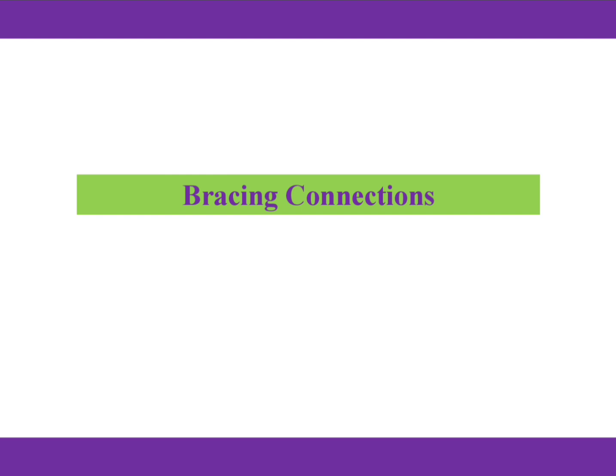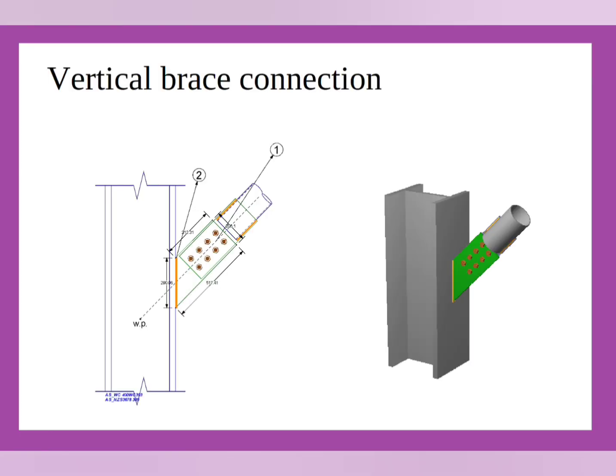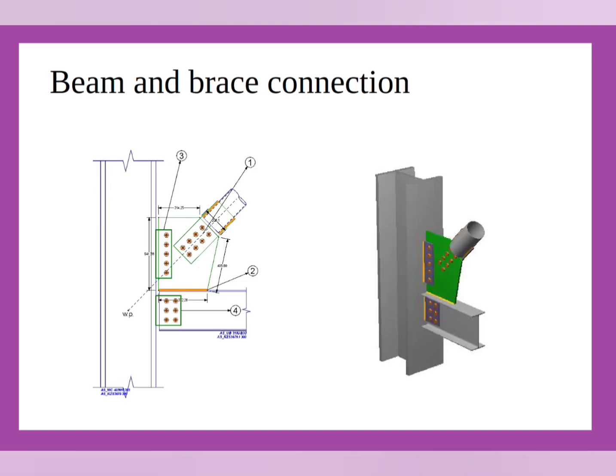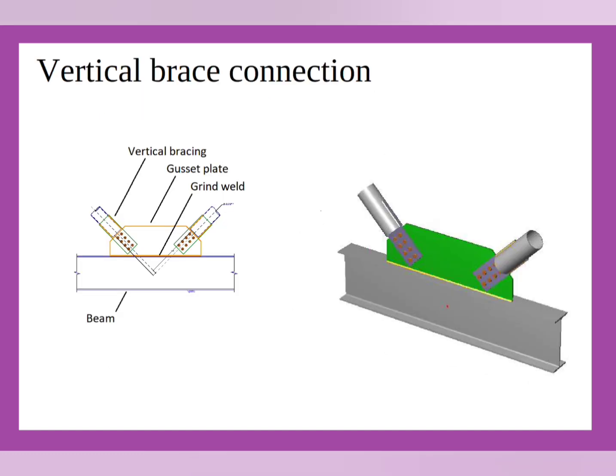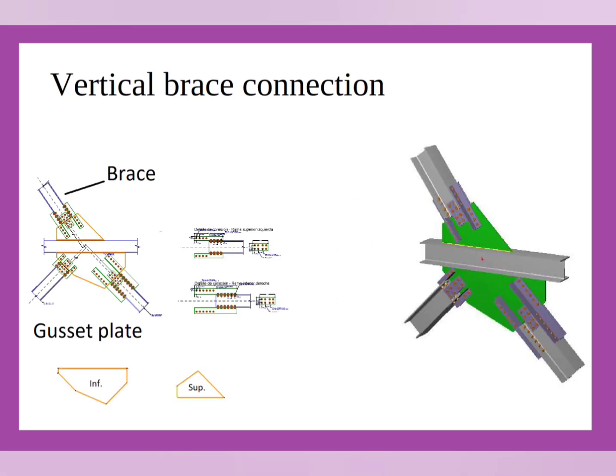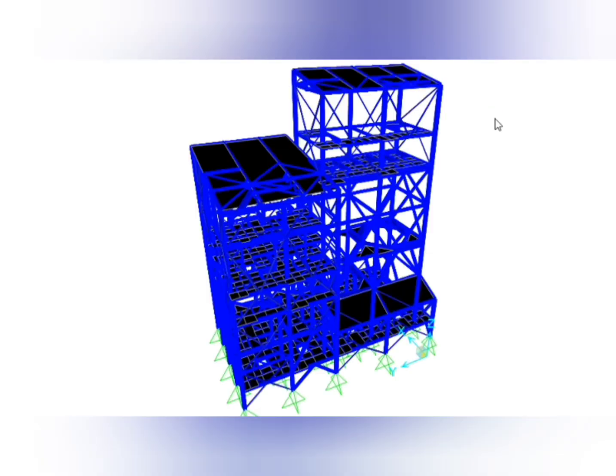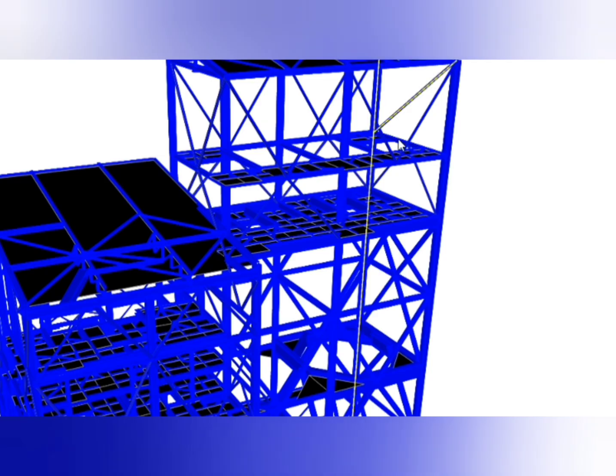Bracing connections. A standard vertical bracing connection is calculated using only the axial tensile force which the bracing resists. Braces should never be subject to compression loads, or at least, because of how slender braces are, the resistance to compression load should not be considered in the analysis. The tension-only tool in SAP2000 can be used to model this condition.